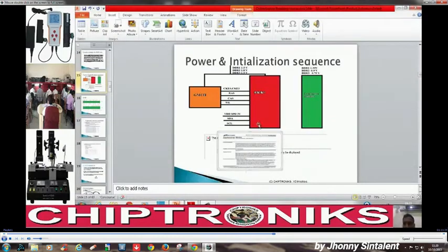So we'll go into our PowerPoint presentation. You can see we have noted all the important specific signals: CKE, RAS, CAS, write enable. So while testing RAM, what should we be concerned about? First, supply voltages, 3 kinds of supply voltages. We must see the RAM reset signal in case of DDR3, and we can also look for these kinds of signals, right? And you can see the RAM reset signal is coming out from the CPU memory controller, right?